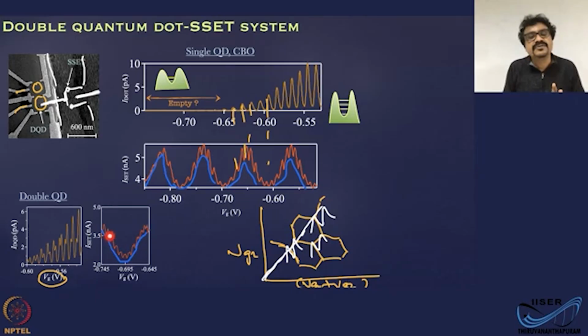That is because it's capturing these cusp-shaped charging events directly. So the SET is sensing each of the charging events, because the reason that you get a triple point is you have two kinds of charge configuration in the stability diagram. Okay, so these two the SET can very clearly resolve. That is what this data is telling.